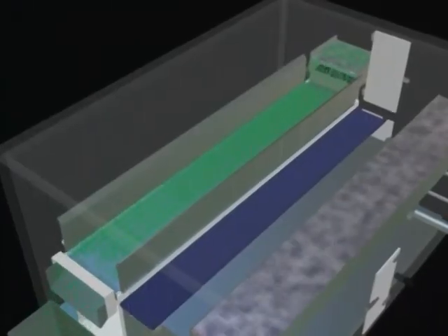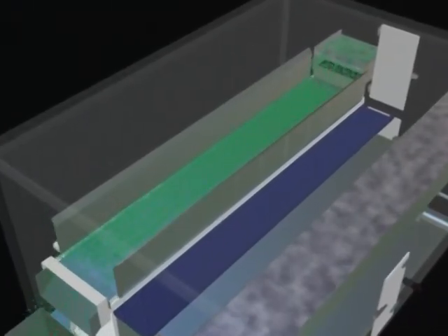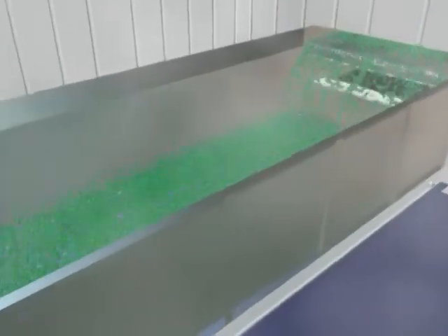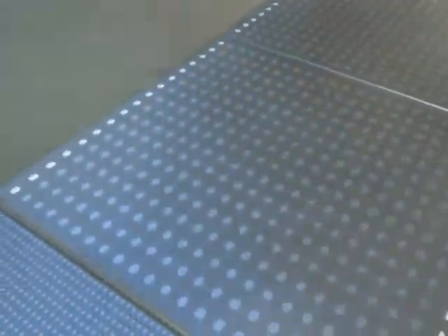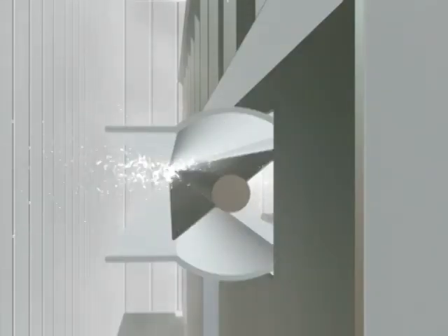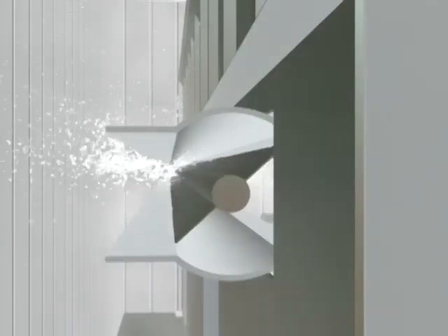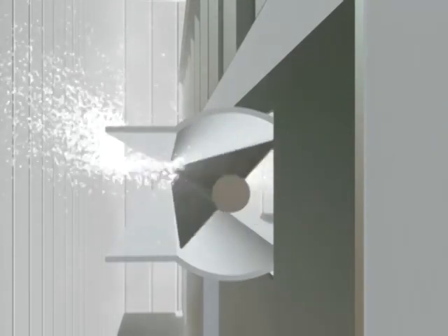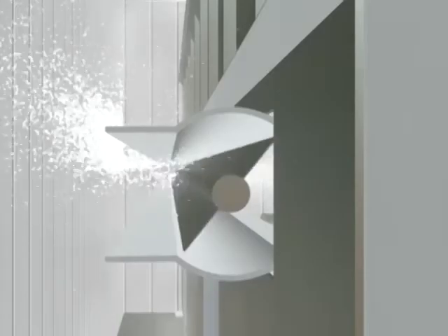The tray oscillates back and forth. The freezer is divided into 3 or 4 freezing zones, with different sized holes on the tray, which create different air pressure and velocity. The air is also pulsed with air pulsators to assure additional product agitation by the fluidization effect. An optional snow belt can be designed at the side of the trays to capture the product frost from the recirculated airstream.